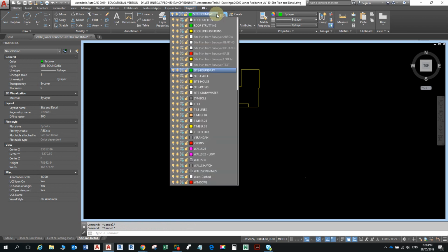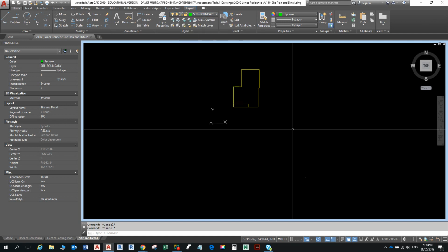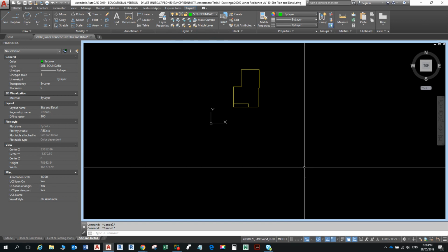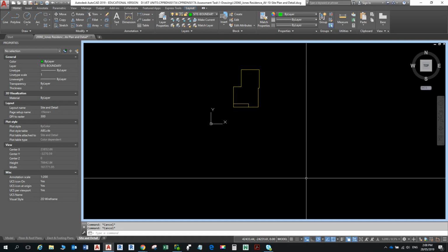In this case, the layer that he was on with the student was electrical or something like that. Change this thing to the layer it should be, then go back and freeze that layer again, and that fixes that problem. If you can't see it, it means you probably put it in a layer that's frozen.